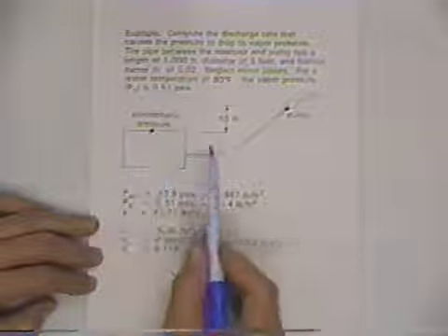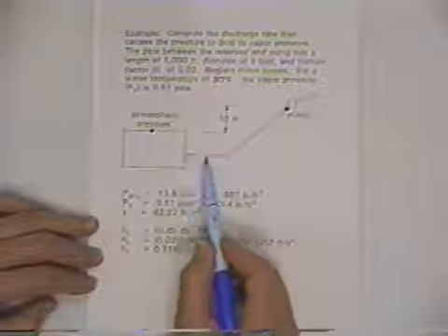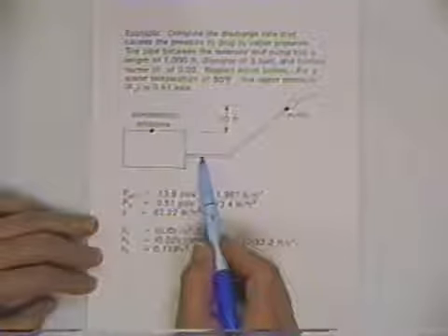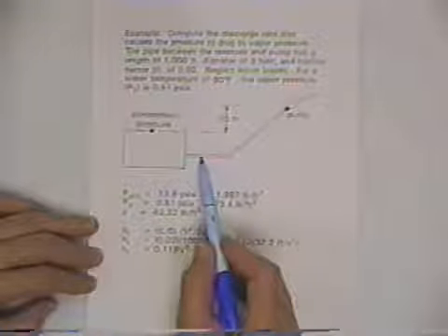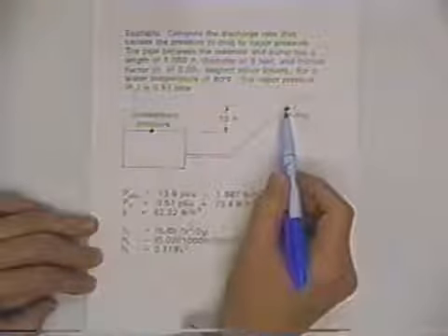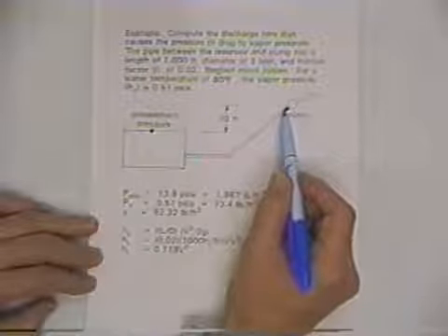We've got atmospheric pressure here, and as we go into here, we convert from zero to a non-zero velocity head. That's going to drop the pressure, and then we're going to have head losses that drop it even more. And then when we come up here, we increase the elevation head, and that's going to drop the pressure head even more. So that's going to be the critical point.